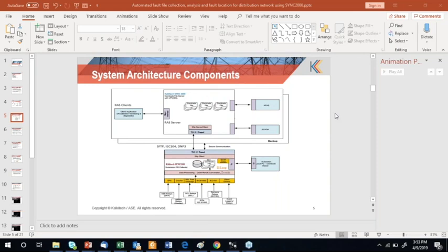Okay, another question is, from the ComTrade file, do you also collect the events and expose them? What I was mentioning is the events from the IEDs directly, but this question is whether, from the obtained ComTrade file, we can extract the events. Because there are digital channels associated with the ComTrade file, can we extract the events from the digital channels of the ComTrade file and expose them as an event file?